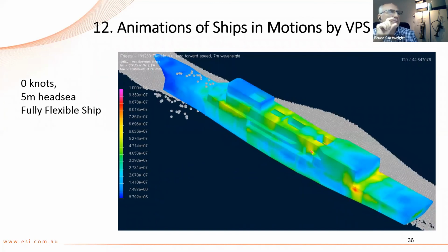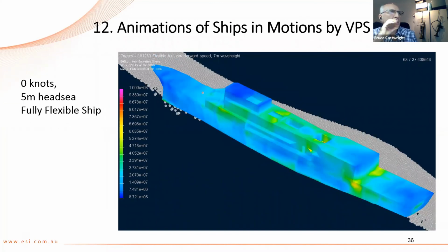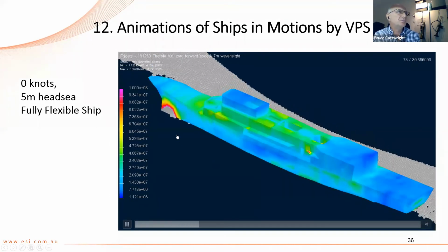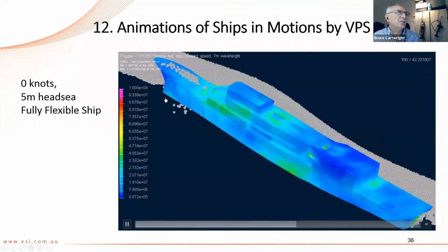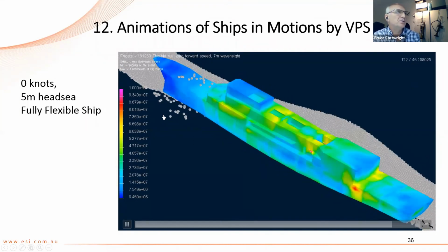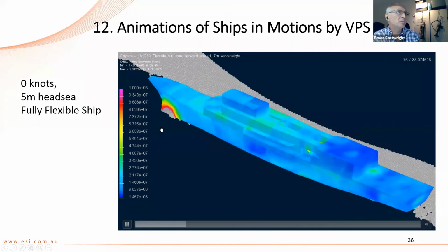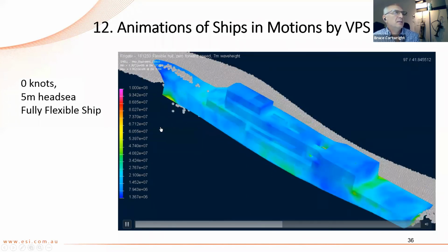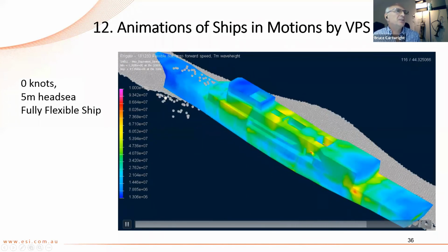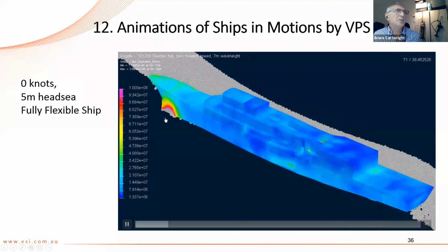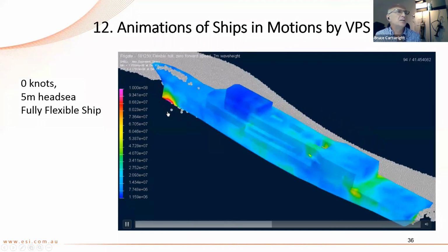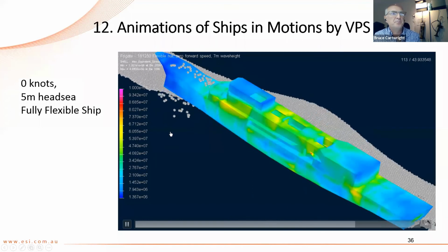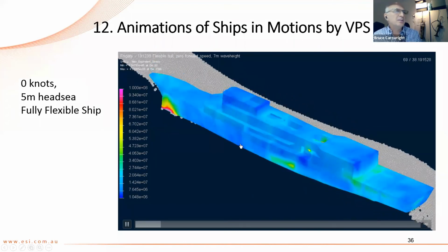Keep in mind the bow of this boat is about 15 metres out of the water. And the foot of the bow is probably 2 or 3 metres below that. So what's happening here is we're seeing some large hydrostatic pressure on the foot of the bow as it goes down into what looks to be almost 20 metres deep. So, you can understand it. It's obviously not a bending load, but when you understand the hydrostatic forces involved, that's what's going on at that point of the boat. So these animations are incredibly enlightening.